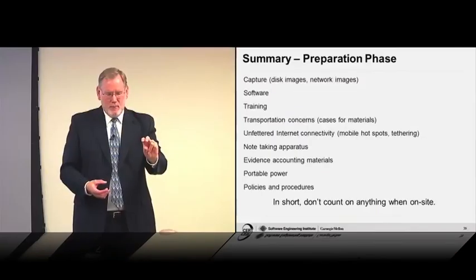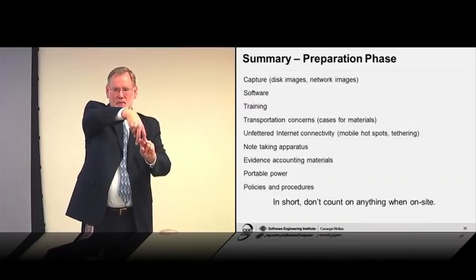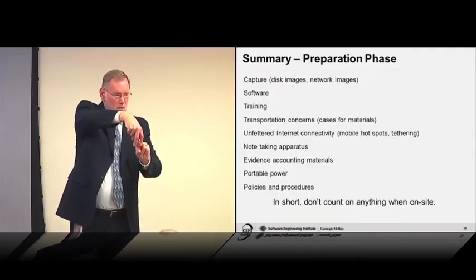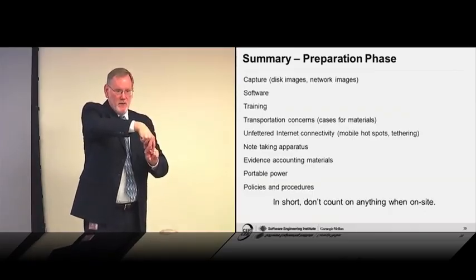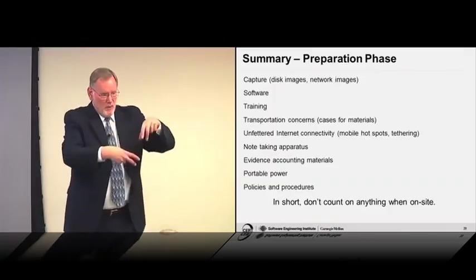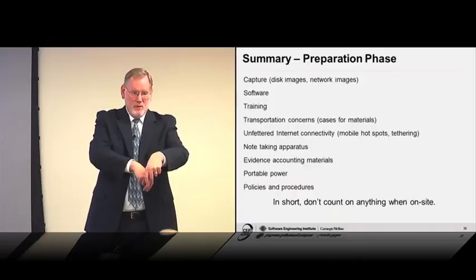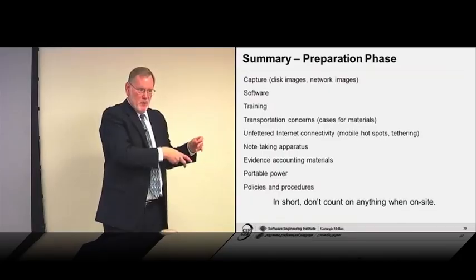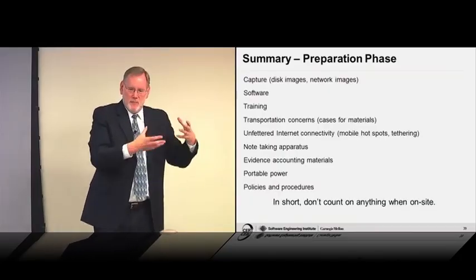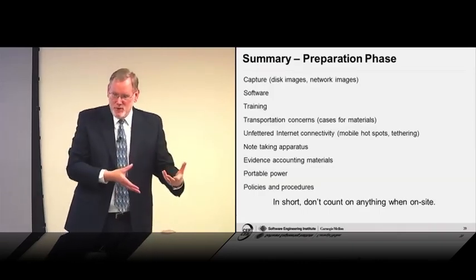If you take a 3-prong plug a little bit out of the wall, there's a tap you can put on top of it, and then you can connect that into your portable power supply so that you can pull the plug the rest of the way out of the wall, and the machine won't lose power. If it's plugged into a power strip, you can plug this other portable power supply into the power strip and then pull the power strip out of the wall, and the computer that's in the power strip won't lose power, but you have to take your portable power supply with you, which means batteries. You have to make sure it's charged.